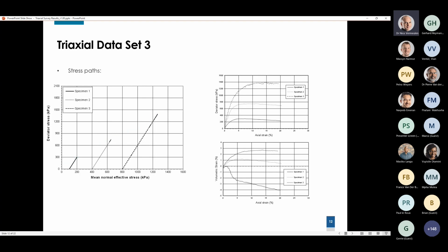So again, blindly fitting a trend line through the endpoints of the data, Excel will come up with something like the blue line, with quite a high cohesion if I look at the y-axis there, and a friction angle. But my best guess would be something closer to what the red line is showing. Again, closer to a cohesion of 0, and you can immediately gather my aversion to assigning cohesive strengths to soils.